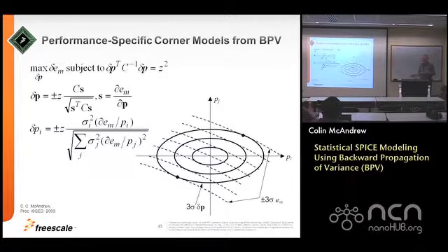So it turns out that analytically, based on first-order variation, and there are people that have extended this to nonlinear variations, you can actually calculate upfront what the values of the parameters should be for those corners. And this is implemented in an internal design tool that we have, and it's called exact corners or something. There's an analysis that people can set up and run, and it would automatically generate this for them in the Cadence design kits.